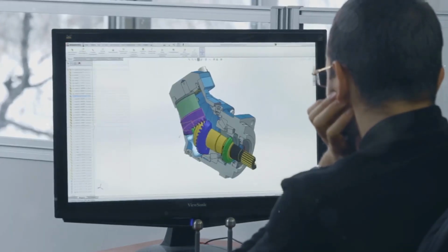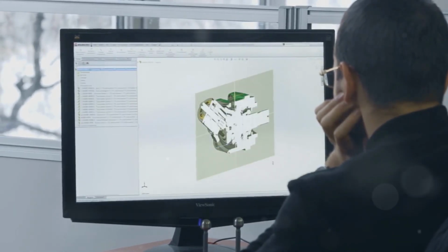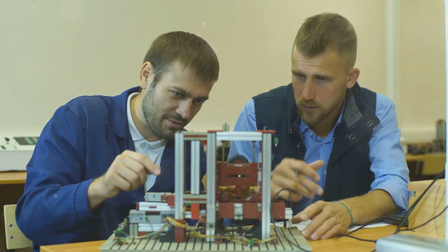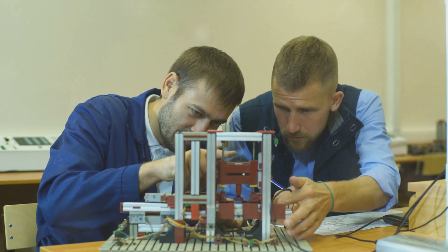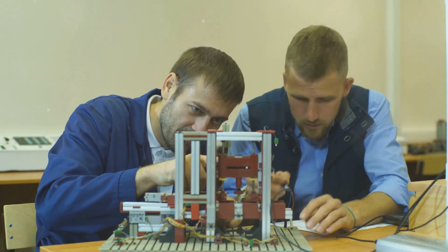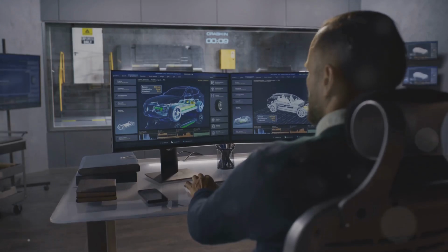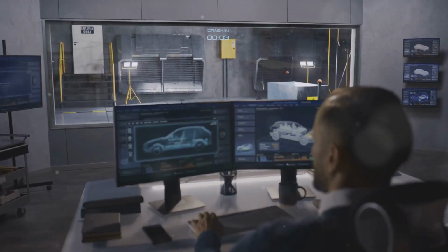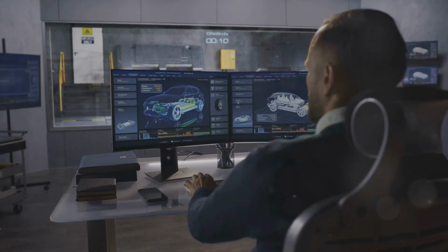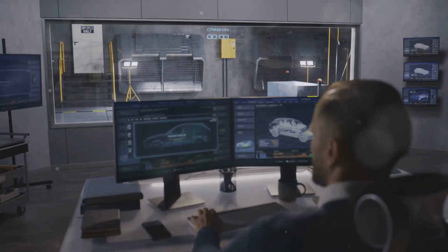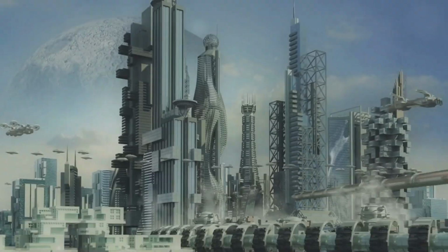For instance, a one-way FSI approach might suffice for problems where the structural deformation has a negligible impact on the fluid flow. However, a fully coupled FSI simulation might be necessary for problems with strong fluid-structure interaction where high accuracy is paramount. The available computational resources also play a crucial role in workflow selection. Fully coupled FSI simulations, while highly accurate, are computationally demanding and require significant processing power and memory. In contrast, simpler approaches such as one-way or two-way explicit FSI are less demanding and can be run on less powerful machines.